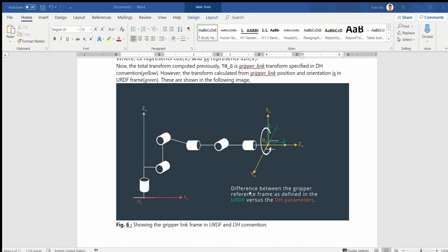Okay, it's really important. For example, you change right here 3.5 for theta 2 and 3.2. Let's see how it creates a new position right here. You can see you can get the position XYZ for any effector. That's forward kinematics. You know all the theta joint angles, and you can quickly find the location of any link, the position and orientation of the last link, the end effector.